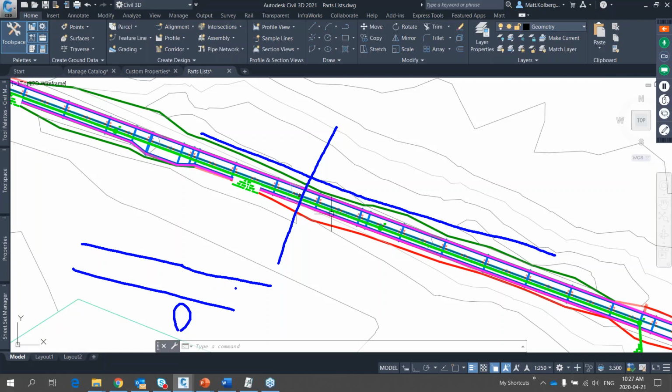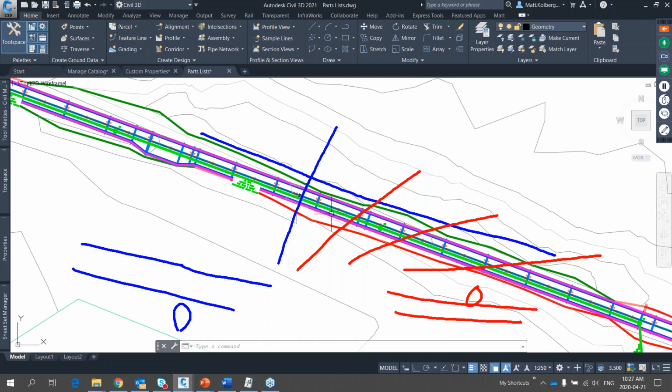That's pretty typical stuff. But what if that crossing pipe is at this angle? What if it's at this angle? What if it's at this angle? Now what? Do you still show it as an ellipse, or do you show it as if it was parallel? Or maybe do you show it both? The point is Civil 3D doesn't know what you want. And so you have to use styles to tell it. So the way I organize my drawings, you have to pick one that's the default, which is the most common, probably parallel. And then in this case, I would come in after and change the style of this pipe to the crossing style so that when it's projected into the profile, it shows up as an ellipse.